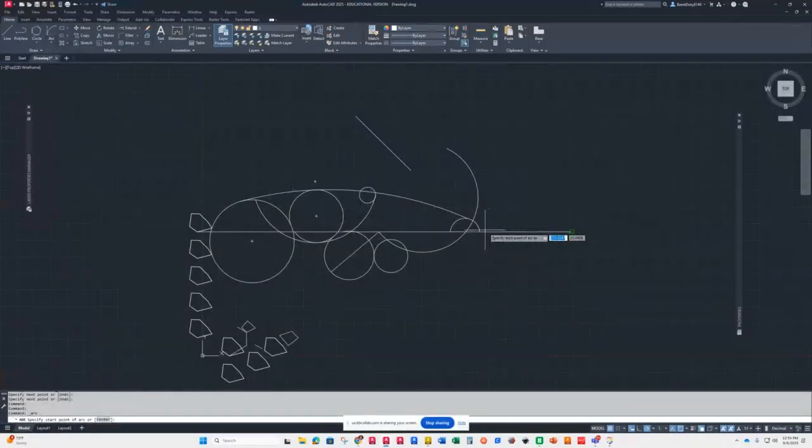And the only reason I use it is because it's an easy way to make a half circle like that. You can just pick 2 ends, move your cursor vertical to where it's completely vertical, 90 degrees, and you can draw a half circle. Now you can also draw a circle, have a line through it, and trim it off. You can do that too. But that's what I use it for. That's about the only reason that I do that.